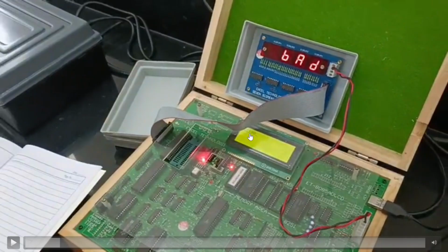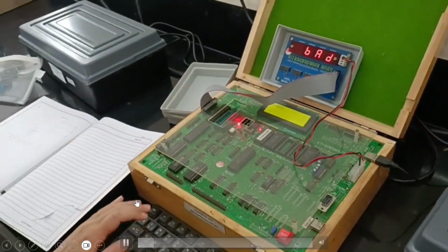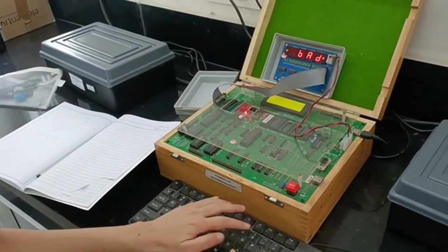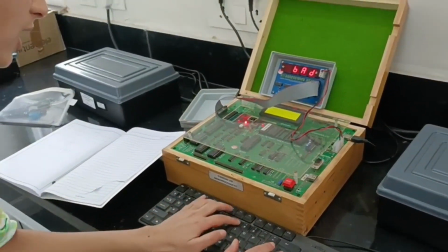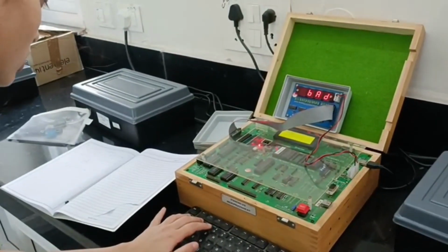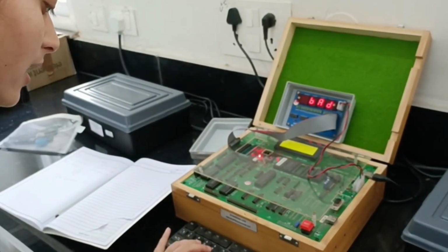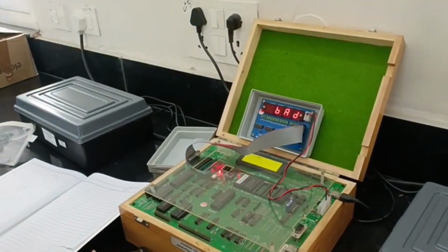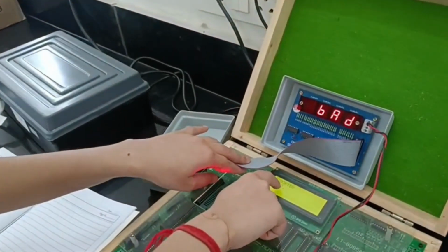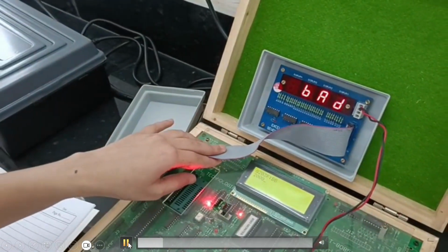You can see 2100, although it is not that clear, but this is the starting address from where we write the customized code. And it goes like this: A1, C0, C0, A2. And then I write G2000, which is the starting position from where the code to activate 7-segment was added.